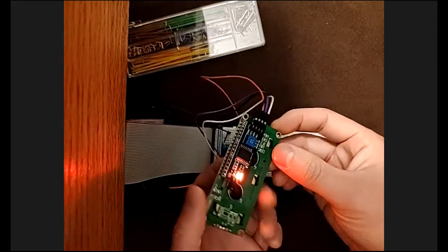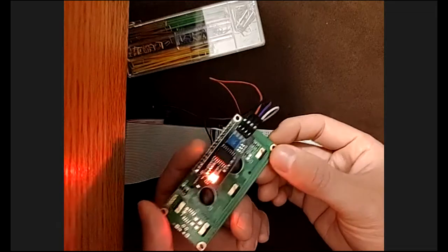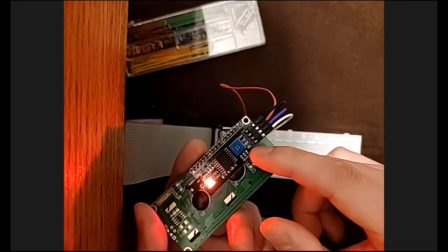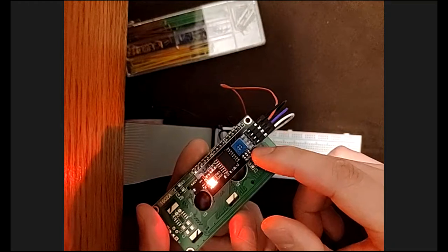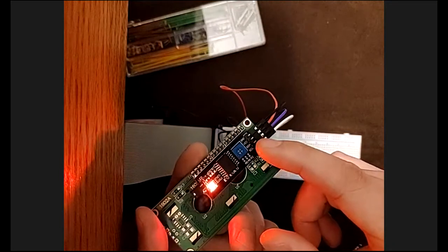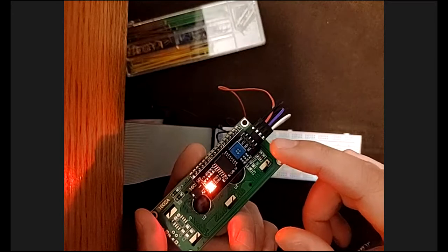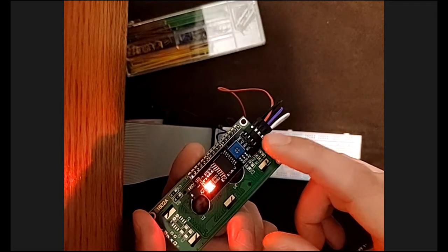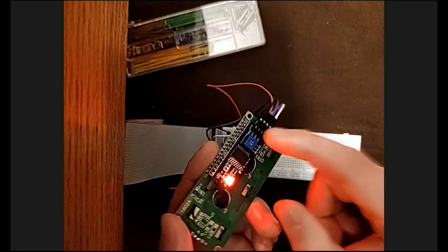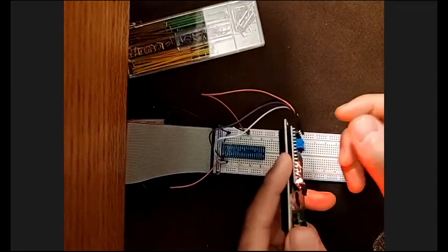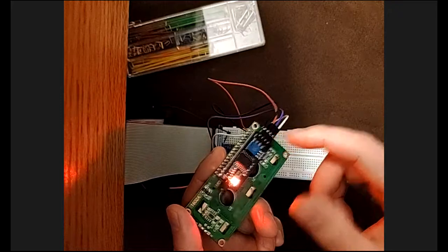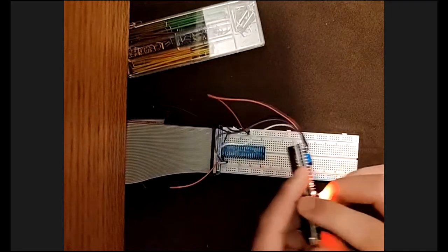So actually, those are named. If you just take this out, you'll read those names: SDA, SCL that we have seen and I explained. They also have the ground and the VCC. Now, VCC is for the positive voltage. We're going to connect VCC to 5 volts here, and the ground goes to the ground, and the other 2, SDA, SCL, excuse me.